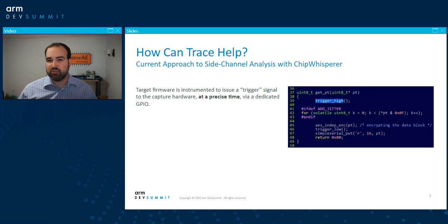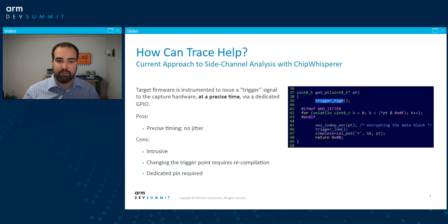So we basically have this special trigger mechanism, and by special, I mean it's a GPIO pin going high, so not super high tech, but it works really well. It's really easy to do, and you can run it on any system. This tells ChipWhisperer that at this point in time there's some interesting data, and to please record the power at this point to analyze it. So we need to tell ChipWhisperer roughly when it happens. We don't always need perfect triggering. We can deal with that later in post-processing. But we need at least a pretty good idea, ideally a perfect trigger. So the GPIO gives us that. There's no jitter. It's very specific. There's code executing when the trigger runs. So this works really well.